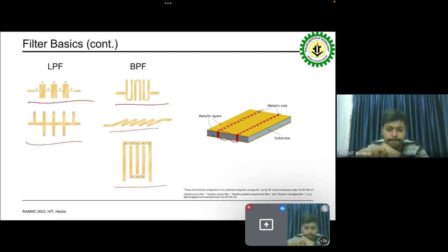And you can imagine using a set of discrete vias like they have here, you're going to end up with some level of leakage in between these, which of course is going to worsen at high frequency. And as you start pushing the frequency more and more, especially beyond millimeter wave, when you start getting into things like W band, this gap does start to become more critical. And your via spacing and diameter might go from something like this down to something like this, where you've even possibly got extra shielding in order to accommodate that high frequency and eliminate some of that leakage.